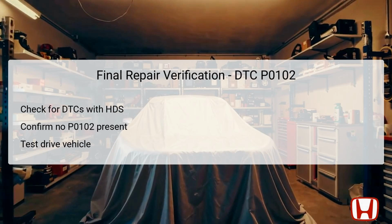To ensure accurate repairs, a final check for DTCs is essential. Utilize the HDS to scan for any remaining codes, focusing specifically on the P0102 to confirm that it has been resolved. Successful verification means that the DTC is no longer present, indicating repairs were effective.